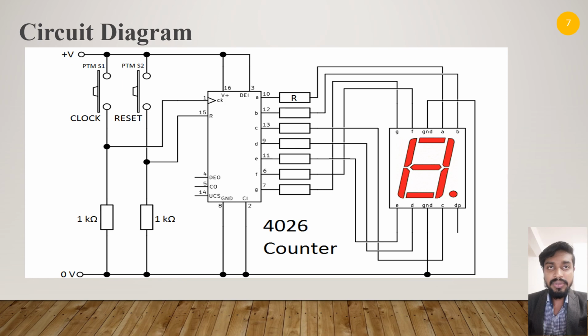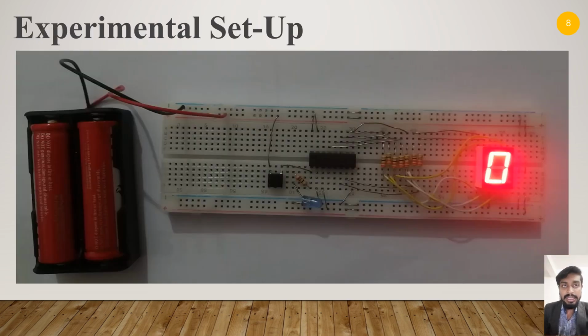The IC is currently used for simple GCSE type project circuits. It comes in a 16-pin plastic dual in-line package for use with stripboard and breadboards. This IC is based on CMOS technology and will operate from a minimum of 3 volts to a maximum of 18 volts. The absolute maximum rating is 20 volts. It can therefore interface with CMOS 3.3 volt and TTL 5 volt systems directly. Since the 7 segment LED display consumes much power, this chip has a special function, display enable, on pin 3, which has to be high when a display is required.